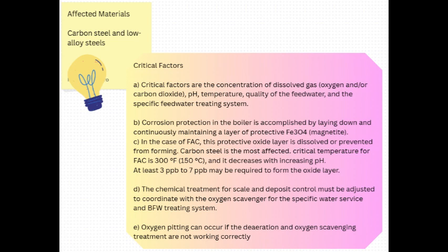That sounds terrifying. I did notice a material science point, though. Adding things like chromium, copper, molybdenum. Yeah. Those help. Yes, definitely. Upgrading to low alloy steels with chromium and molybdenum significantly boosts resistance to FAC. It makes that magnetite layer tougher or helps it reform faster. So better materials are an option, but usually expensive, I assume. Very. So before you rip out piping, you focus on the chemistry.